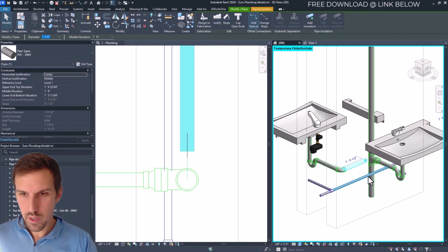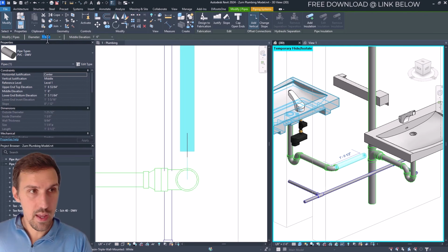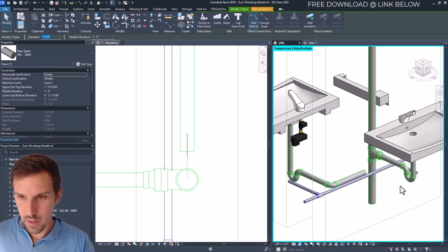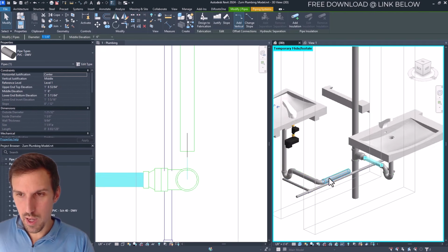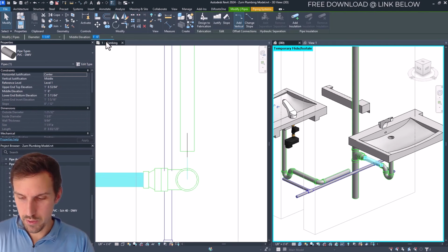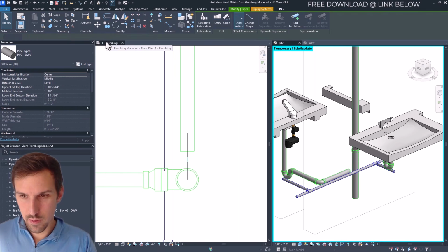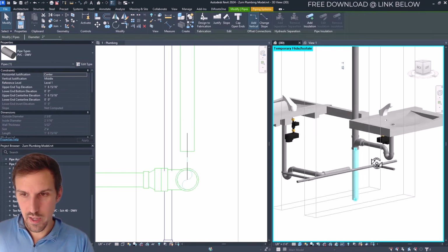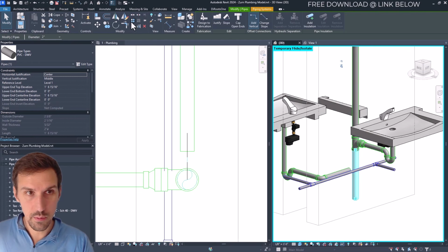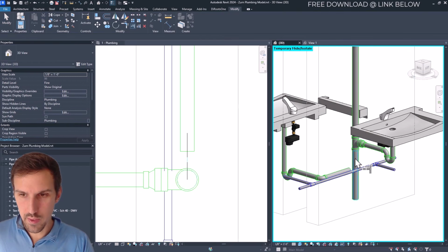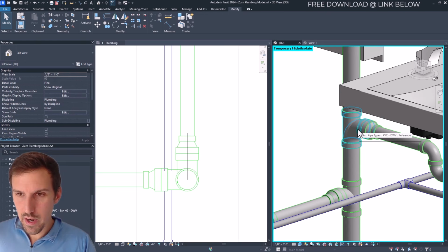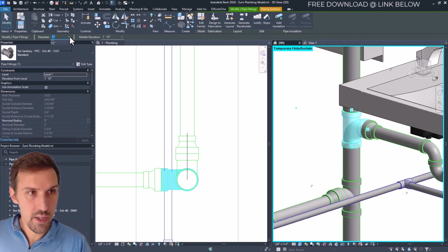So all we have to do is click on the pipe and then we'll just drop it. So instead of 1'6", maybe let's drop it to 1 foot. And then maybe we'll raise this one up a little bit. So let's raise this one up to, I don't know, 1'10", something like this. And then let's make that connection. So we can use our Trim Extend single element tool, this one right here. And then we'll click on the pipe we want to go to first, and then click on our branch, and look at that. Now these fittings right here are 2-inch.